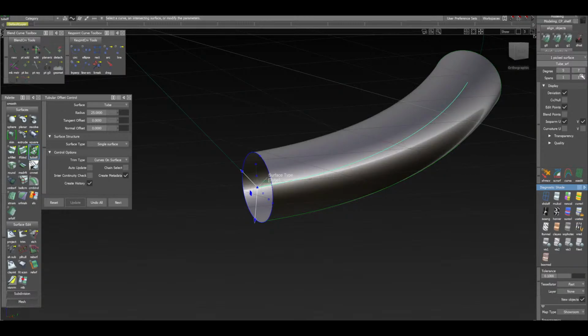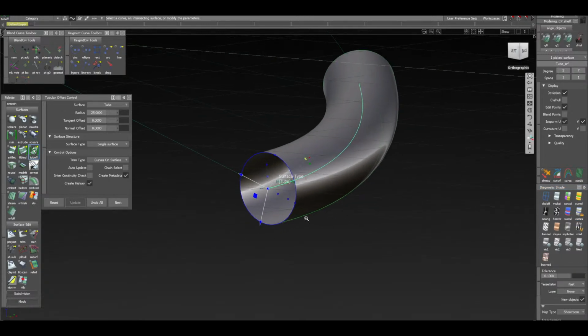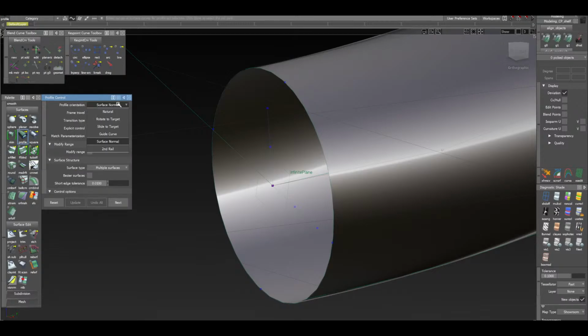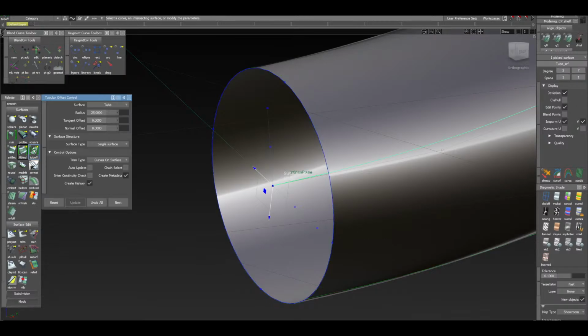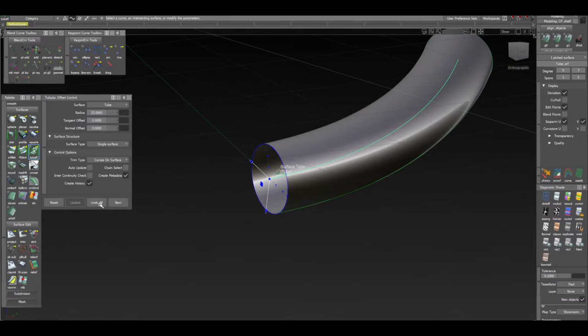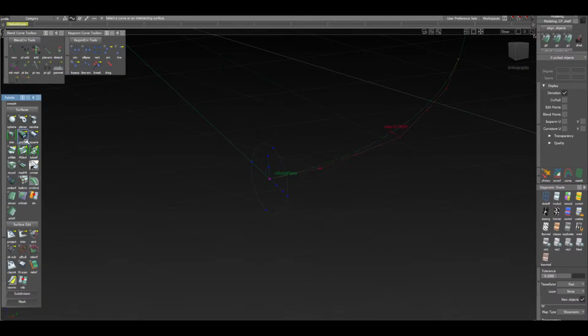And we have one section, you'll see it's a 5/7, one single span, and it falls precisely on the circle that we've created, the geometrically accurate circle. But if memory serves, there should be a way. It's the profile tool. That's what it was. Okay, I'm sorry guys. I was mixing up tools here, between the extrude and the profile. So again, we could just use the fit curve we've created to manually create sections of tube, like I've just showed you a couple seconds ago. Or we can use the profile tool.